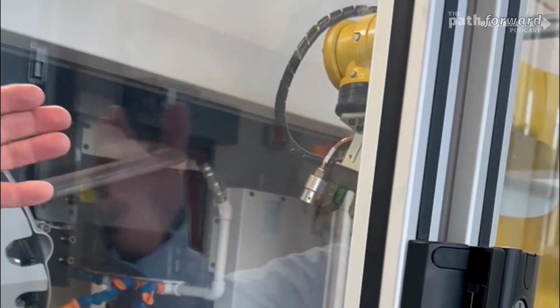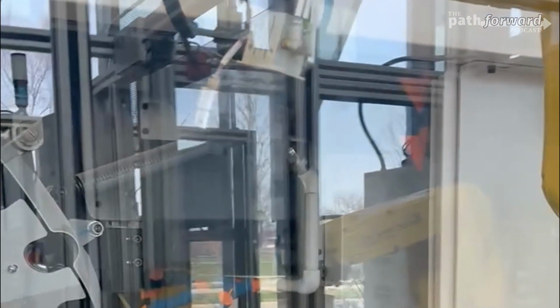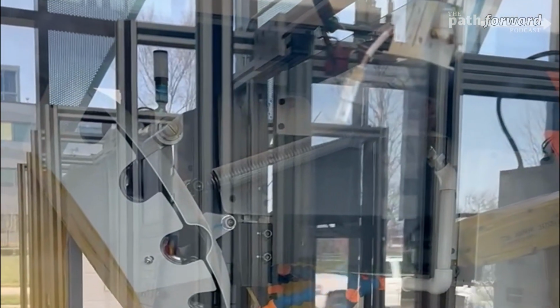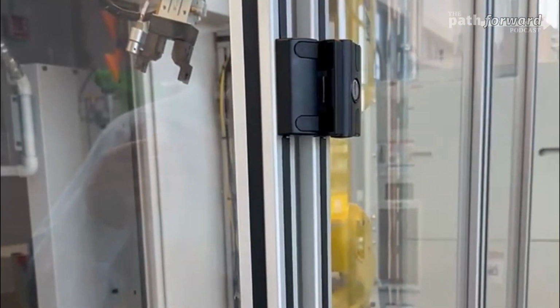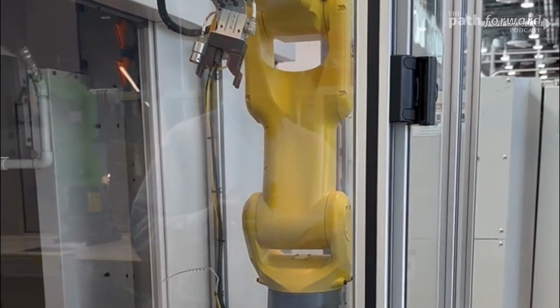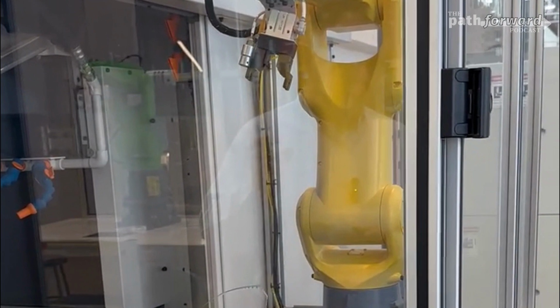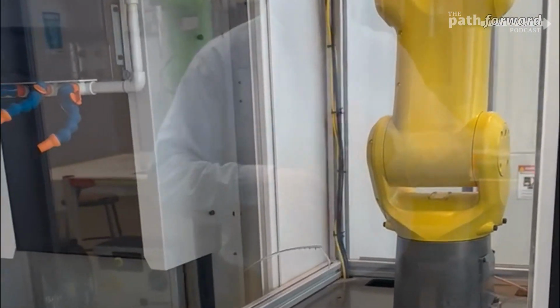In this case, the robot is loading and unloading the CNC machine, and you'll learn how to adjust the robot, start it up if there's a fault, shut it down if there's a problem. But most importantly, over time in a robot, many times things change and you need to adjust the positions of the robot or how it's picking the part up. You'll learn how to make those minor adjustments in the function of the robot.